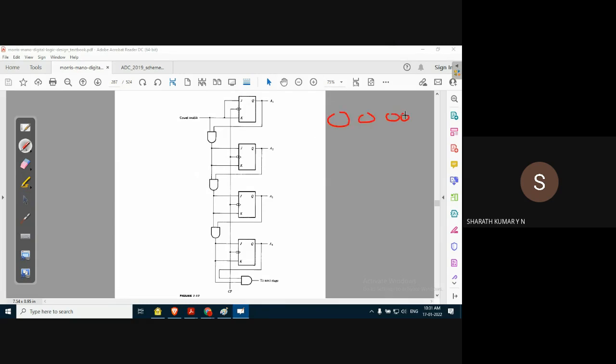By default, when we say counter, we consider it an up counter unless we specify it as a down counter. So for a 4-bit counter the next state should be 0001. Since it is a binary counter, it will go from 0000 up to the final count of 1111. On the application of the next clock pulse, the count should be reset back to 0000.